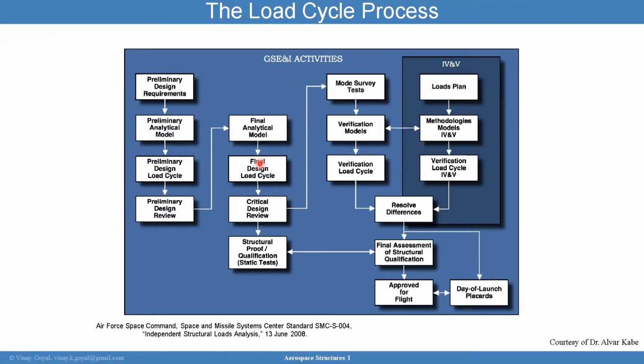And there are also hand calculations I'll be showing you today on some of those loads that need to be projected and predicted. This feeds into a critical design review, and the reason these loads need to be fairly mature is because that's going to step into my structural models, and I want my structural models to produce the correct margins.